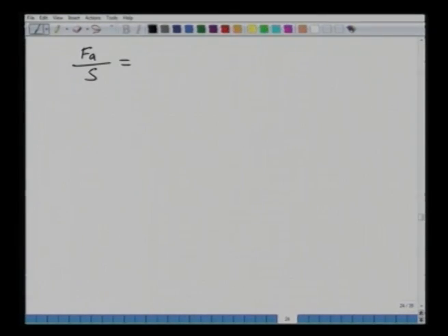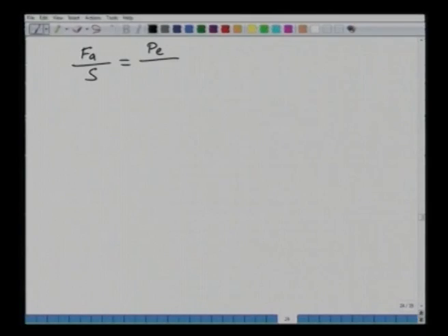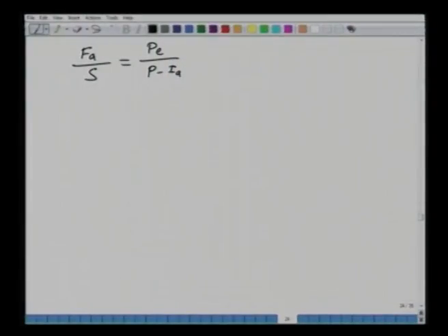What is the actual runoff? The excess rainfall, that will become your actual runoff, direct runoff, divided by the total or the maximum possible runoff. Well, it is the rainfall, and what part of the rainfall does not become runoff? Well, it is only the initial abstraction. Initial abstraction does not contribute anything to the runoff.